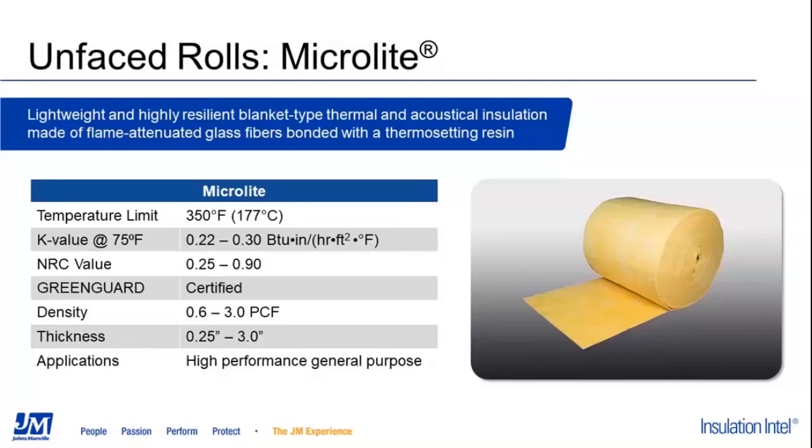So back to the Microlite as a flame attenuated product. It has a temperature limit of 350 degrees Fahrenheit, so a bit higher. K values ranging from 22 up to 30, acoustic values from 25 to 90. It is also a GreenGuard certified product. Density ranges from 0.6 pound up to 3 pound density, and thicknesses from 1/4 to 3 inch in thickness. Again, a high performing general purpose fiberglass roll product.